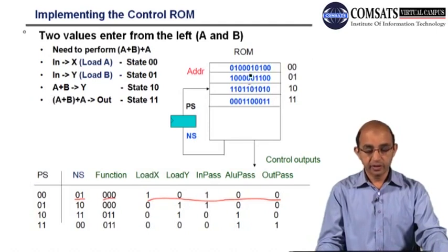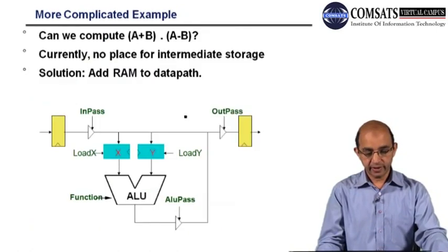So we have a total of 4 sets of instructions within that ROM, and these are 0, 0, 0, 1, 1, 0, 1, 1. So 4 different locations, and this is the present state, this is the next state, and this is the state storage element, that can store the state.